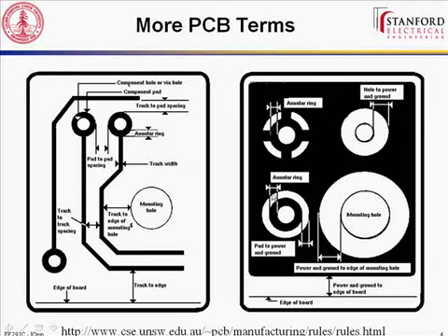So on this bottom one, remember that the white is where there's no copper. So you have an annular ring just around the hole, because this is the hole that you drill, and this is the ring itself. And then this white part has no connection. So you can solder just fine to components on the other layers, on the top and the bottom through this hole, because it's not sinking the heat into the copper. On this one, you have the no copper just around these small parts with these small connections going out, and this allows you to solder in this hole, right? Because it allows this inner annular ring to get very hot before you wick away all the heat into the plane layer.